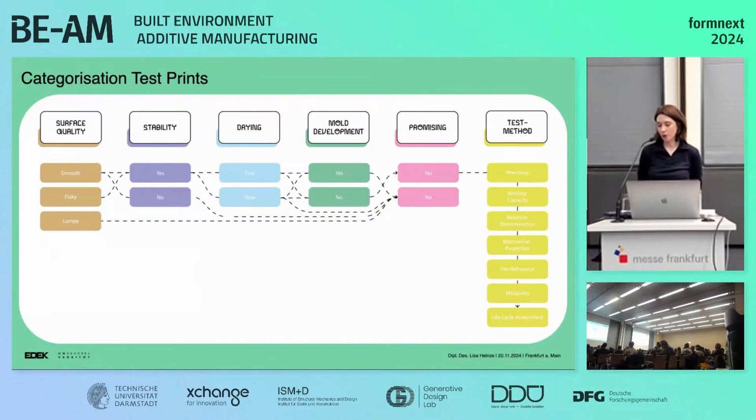In order to generate the necessary data, we have developed this categorization system to determine which material formulation can be tested using the usual methods for testing rheology, binding capacity, moisture determination, mechanical properties, fire behavior, millability, or finally, life cycle assessments.